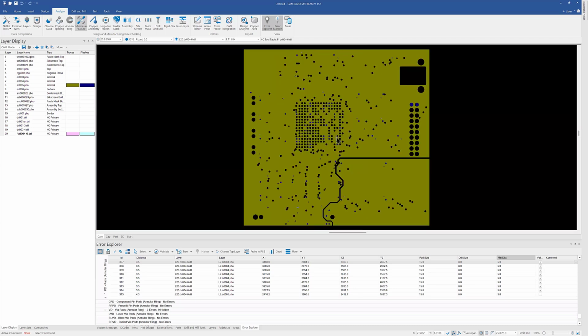So that's kind of the analysis methodology in our tool. It works with ODB and 2581. Of course, we don't have to do a lot of that setup if we bring in intelligent data because the layers are defined, the layer sets are defined, the net lists are already extracted, the IPC net list is already in there. So a lot of the manual setup needed to run analysis, and it's not real manual these days, is done for you when you bring in intelligent data.